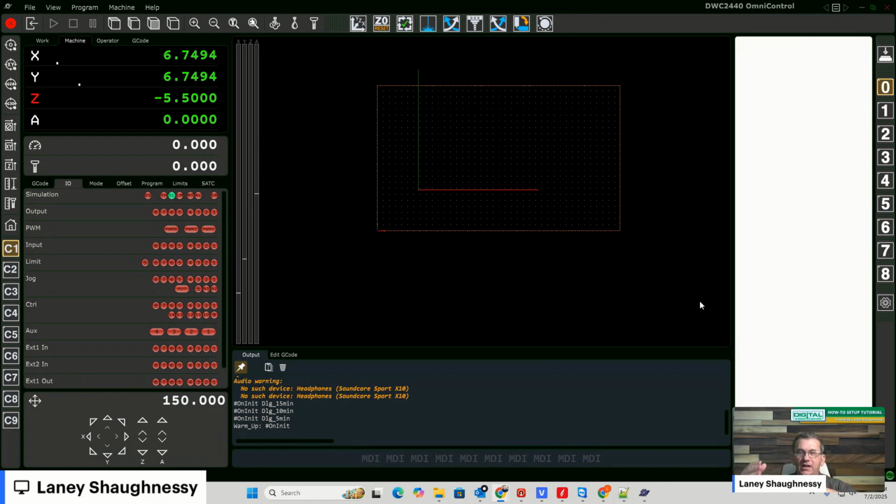When you're running a toolpath with multiple tools, the unit will present itself to a certain location for you to change tools, and then it will go back to that fixed sensor, measure itself, and continue the carving.